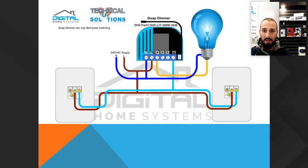But again, if you're not using two-way, simple, just exclude one of those switches and make sure that you run it from the live and the neutral, running into your device, into your switch, and then to the light bulb itself. Now, one thing to bear in mind with dimmers though is that they do require a minimum load. So every now and again you might have the little error in calculation, where you might not have figured out what the minimum load is for that lighting circuit.